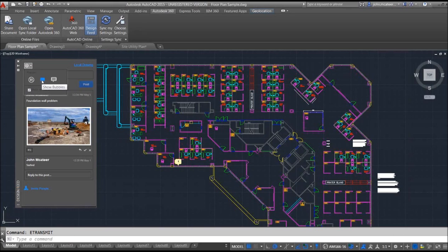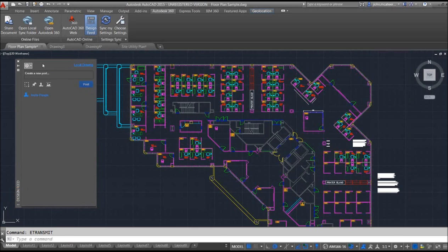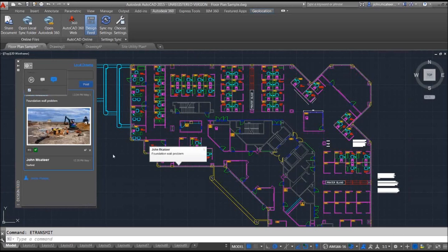and you might have a varying number of these around the drawing. But also you've got show extended bubbles, so that will just show the name and the actual comment itself. When you mark these guys as being resolved, just in your options up here, there's a small little tick box for show resolved, and that will just show the current ones. At any point in time, show the resolved markups, and everything will pop back up.